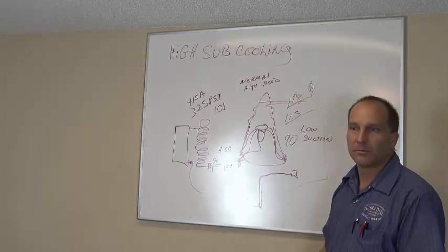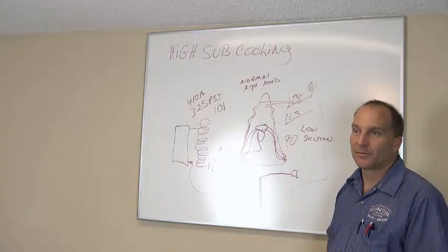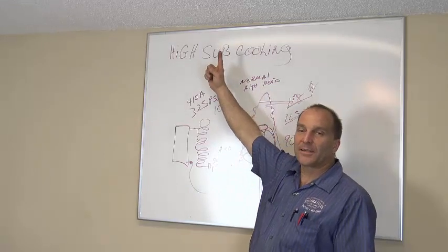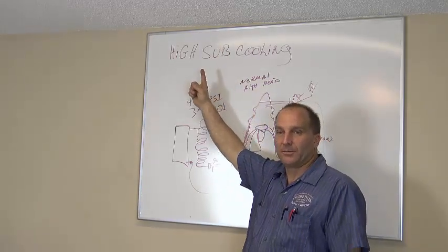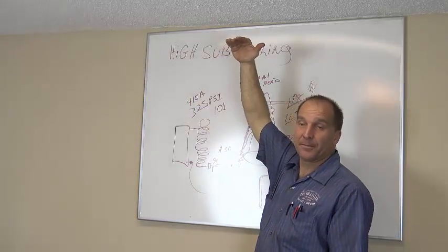I'm good. I'm good. What's his head pressure doing? It's going up. He just jacked up his head pressure. What's the subcooling doing? Getting larger. Your subcooling raised up high.